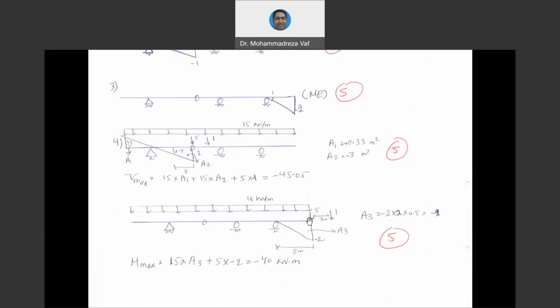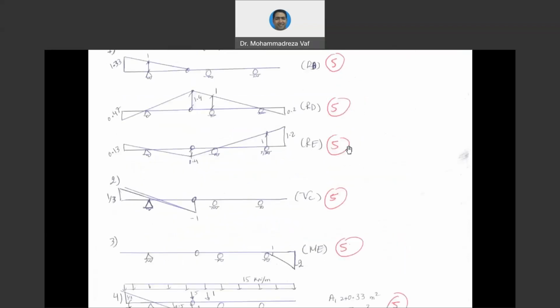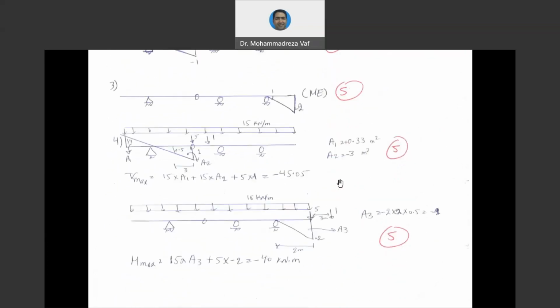One of them is the one that can be seen here, meaning one of the point loads is at the end of the cantilever, and the second one has already passed the bridge. So for this case, you get 5 multiplied by -2, which is -10. You may examine another case, since this one is 2 meters and the distance between our point loads is 3 meters, according to the test.